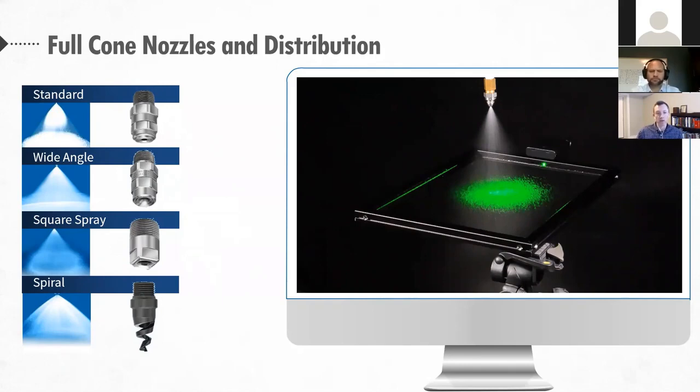And so a wider spray angle, regardless of the nozzle type, would typically lead to, for hydraulic nozzles, a smaller droplet size, just because you've pre-filmed or pre-spread out that material a little bit to help it atomize once the drag forces take over. Yeah, that's perfect. Thank you, Kyle. And the last piece on the hydraulic nozzle is we're looking at a fine mist on the next slide here.